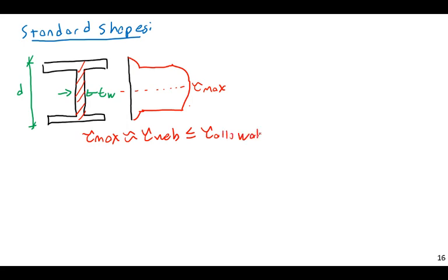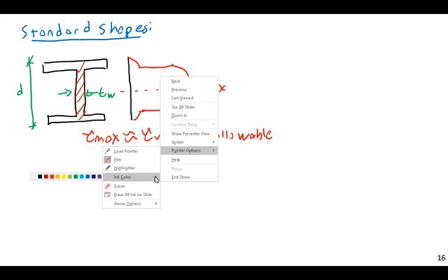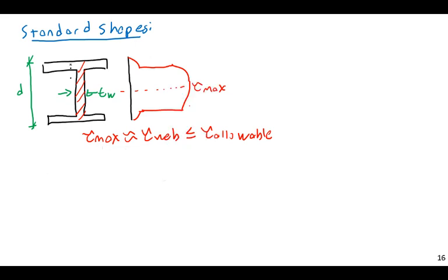So again, even though we know there is a great deal of error in our shear calculation at the flanges, ultimately it really doesn't matter because the web is carrying all of the shear anyway. So these equations are actually fine. If I ask you for the shear at some location in a web, just use these equations, even though we realize there's some error in it, and that's fine. It's not critical there anyway.